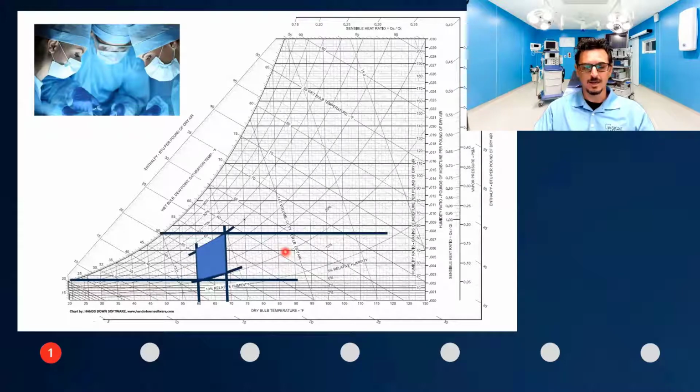And this gives me an idea of the top level dew point in the space and the bottom level, which then I could think about, okay, this rules out standard DX equipment, or this is obviously in the desiccant area. And this is what I'm doing here with this exercise. So in this case, the bottom range of those temperatures and humidity levels is 20, and the top is 49.